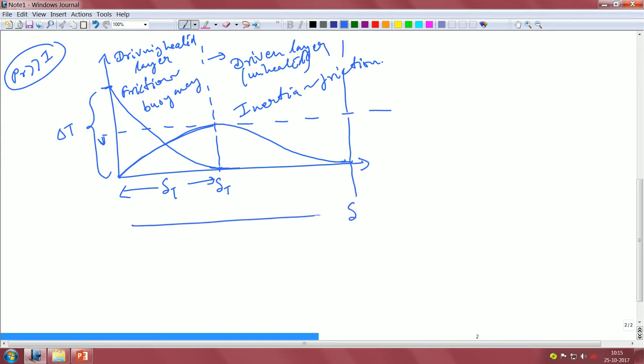So, this delta is definitely greater than delta T, it is a Prandtl number much greater than 1 situation, remember. Here two things: one is that the velocity scale is determined by the heated driving layer. But on the other hand, the driven layer thickness, the total thickness that you are actually dealing with, is determined by this balance between inertia and friction, outside of this delta T.